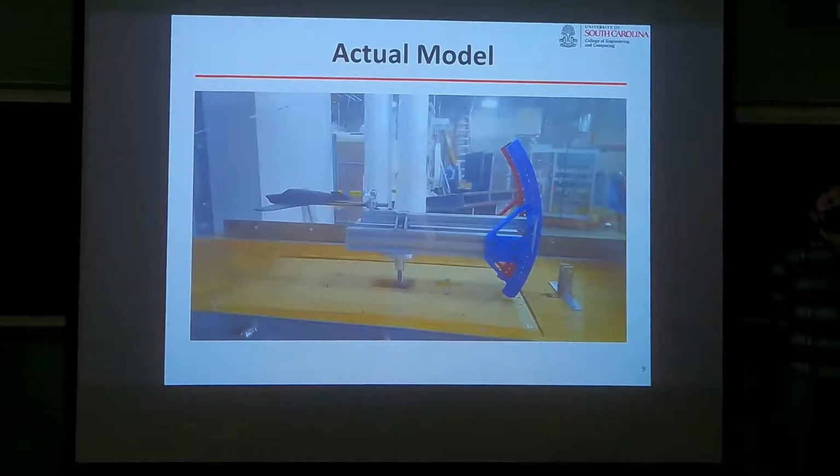It depends. There's no best design, like a low winger or a mid winger. You could have a high winger, a low winger, or a mid winger, whatever is cheap and good for maintenance. High wingers have a problem for maintenance personnel, and for low wingers it's easier.